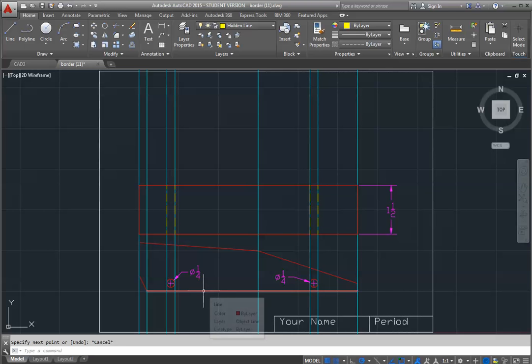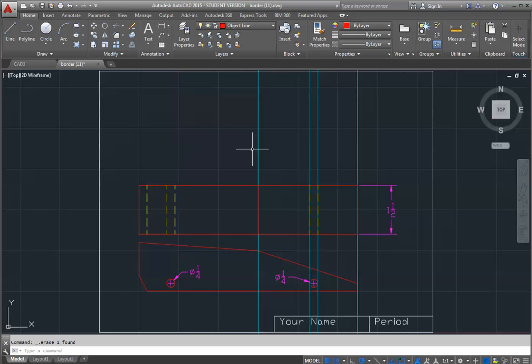Okay, do I have any other hidden lines left? Yes. Where? The back edge where it slips. All right, the back edge where I'm looking down at it from the top. That's a hidden line. That's correct. Now, do I have any object lines left? Is this an object line or a hidden line right here? That's an object line, because as we turn it, we can actually see it. So I'm going to come up here, and there's the object line. Now the next thing I do is go through and delete all of my construction lines.